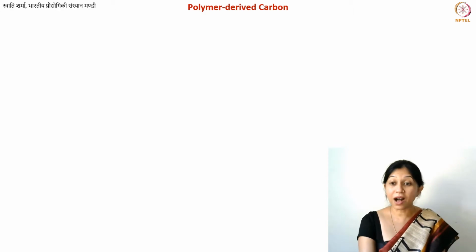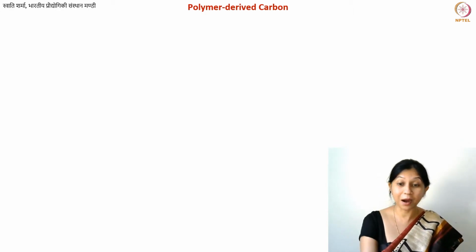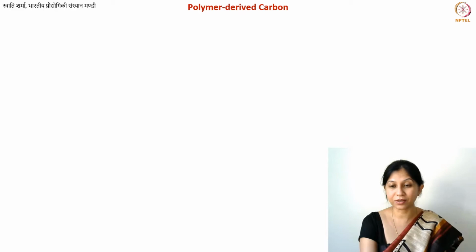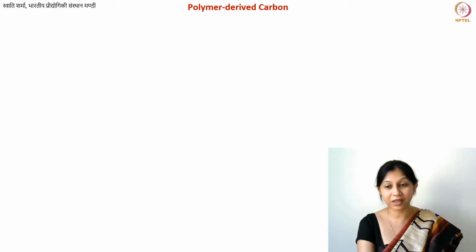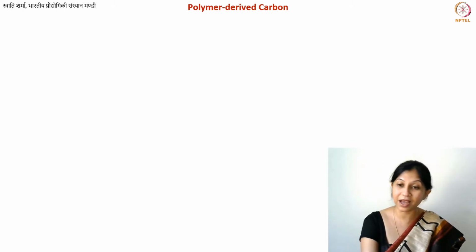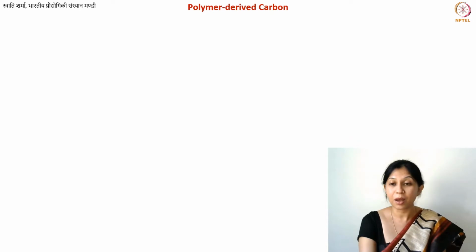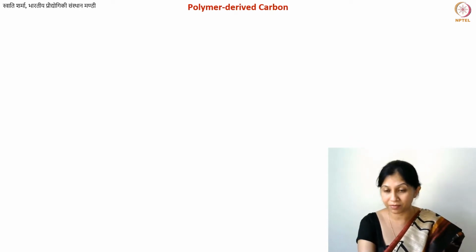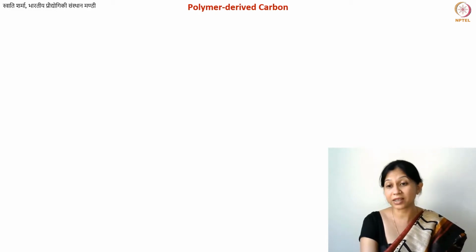Now we move on to other forms of industrial carbon materials, bulk industrial carbon materials. We discussed a lot about graphite, and there are various methods of preparing it. You can make graphite from the pyrolytic carbon that you get from gaseous hydrocarbon precursors, and you can also convert polymers into graphite. Not all polymers, but some polymers via heat treatment, and you can also call it pyrolytic carbon because this is obtained after the pyrolysis of a polymer, which is also an organic material, not necessarily gaseous.